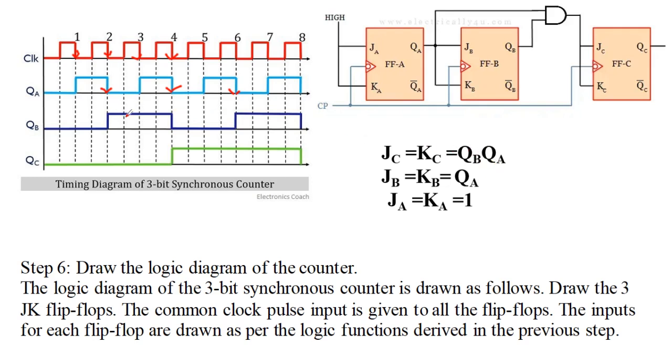So now we will check on which clock pulse your QB and QA become logical 1. On the first clock pulse both are zeros. On your second clock pulse, 0 1. On the third clock pulse it is 1 1. 0 is on QA, 1 is on QB.